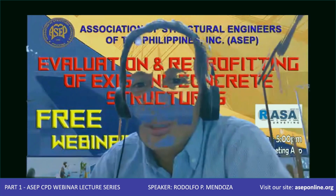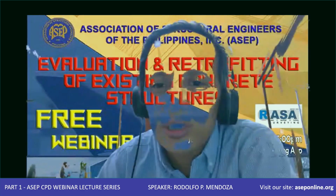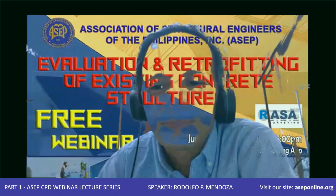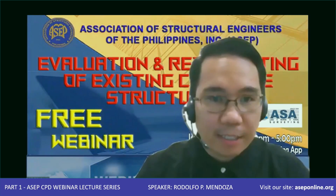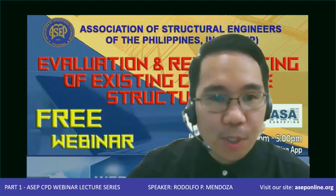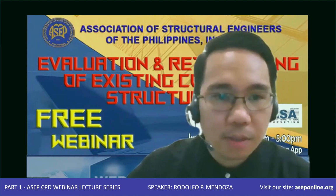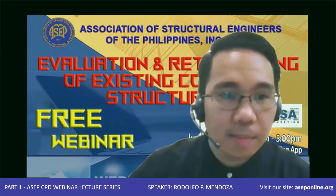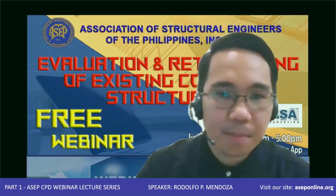Another question is, what should be considered in choosing concrete models, since there's a lot of existing concrete models? Well, to be honest, there are no real restrictions, but of course you would need to adopt those that are commonly used by several authors in practice. And of course, one of the commonly used models is the Mander et al. model in modeling concrete behavior.